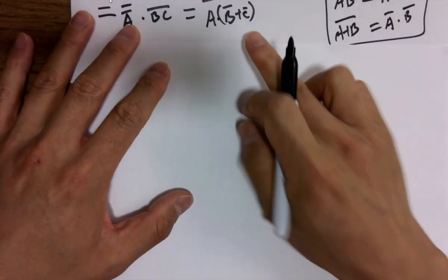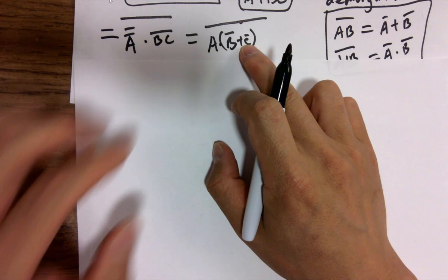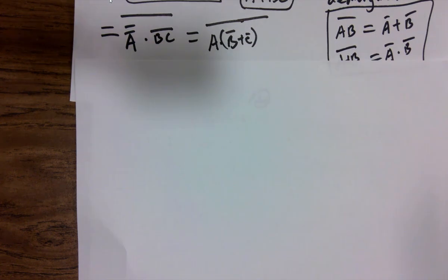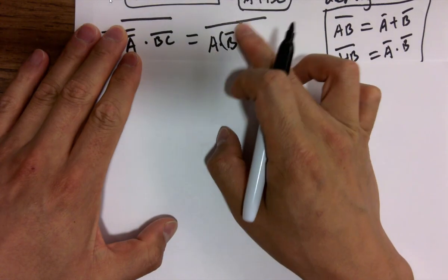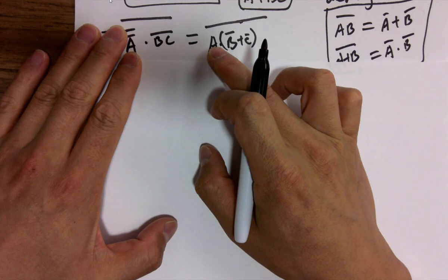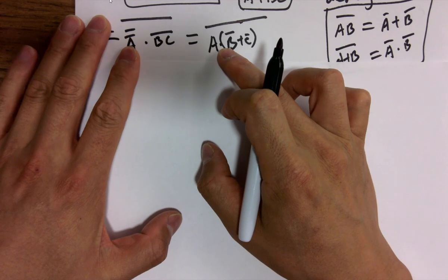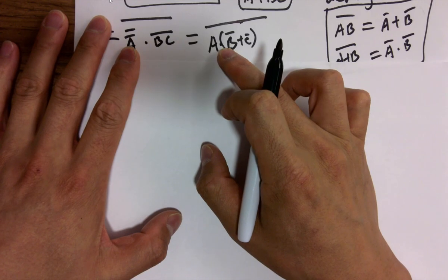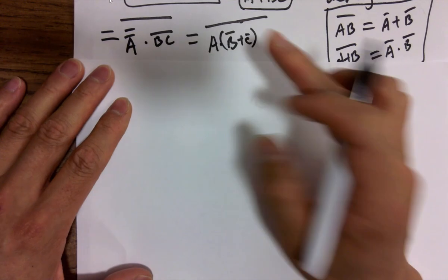So that's the OR logic. For OR logic underneath the bar, we need series PMOSes and parallel NMOSes. And the whole thing here is being treated as one entity, and this guy, for AND logic underneath the bar, we need parallel PMOSes and series NMOSes. Okay? Let's do it.